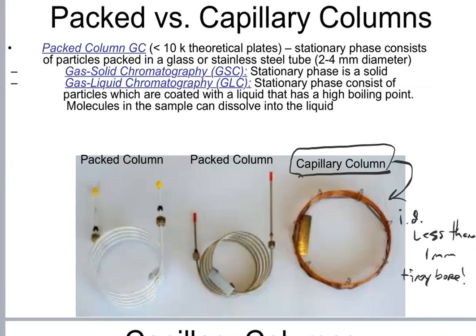Difficult to see unless you look at it under a microscope. And they're actually made out of a glass called fused silica. And they produce these by taking a glass tube, heating up a section, and then basically pulling it very, very carefully down to very, very small internal diameters. The outer diameter is usually somewhere around 400 microns. And you can see it looks brown. That's actually the glass tube. And they coat it with something called polyimide, which actually gives the tube really interesting properties.